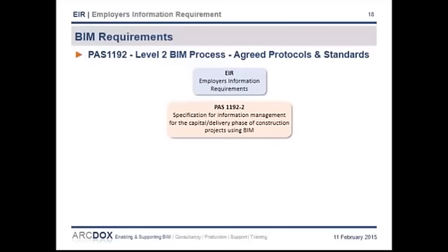So hopefully you're convinced now that the EIR is important. So let's look at what it is and how it relates to the overall BIM process as set out in the PAS 1192 specification. I've really come to believe that the EIR is one of the most important pieces of the puzzle, as it is the one document that can drive the process from start to finish, and the one document that all parties have to respond to, be you designer or contractor. It also has to be generated at the start of the project. It has to carefully consider what's going to happen throughout all the stages of the project, and ultimately it has to set out what has to be delivered at the end.